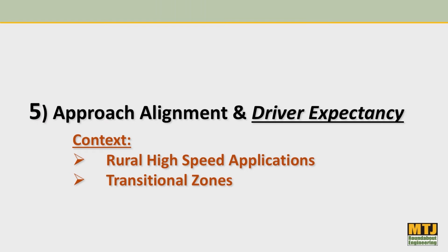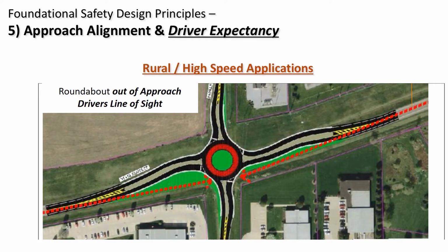To the two-lane roundabout when capacity is necessary. So when we look at, we're going to switch gears here to more of the transitional and high-speed applications and how important driver expectancy is. Okay? We know that as an industry, our roadway design standards are predicated on that, our highway design standards for speeds and curves and sight distances, etc. But with roundabouts, we sometimes ignore those things.